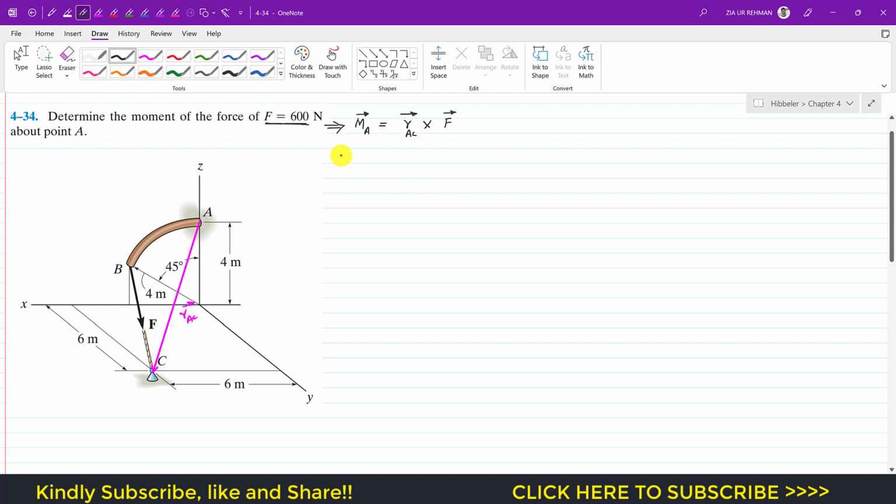First of all, we have to find RAC, which is the position vector from A to C. To find the position vector from A to C, we have to travel along the x, y, and z to reach that point C from point A. To reach point C from A, we have to travel 4 meters in the negative z, or the negative k. So I will write minus 4k. And then from here, we need to travel 6 meters in the positive x, so I will write plus 6i. And then 6 meters in the positive j, or the positive y. So I will write plus 6j. So this is the position vector from A to C.